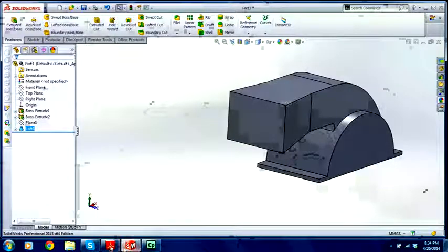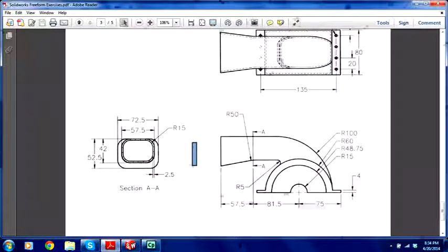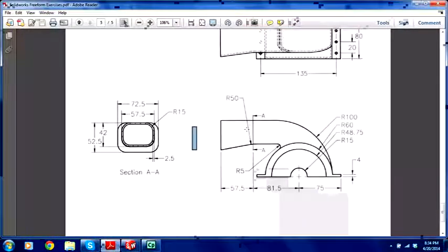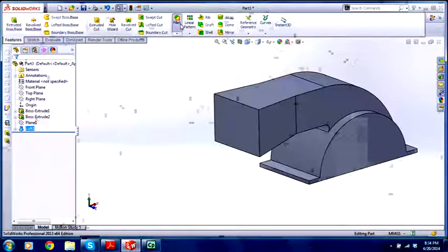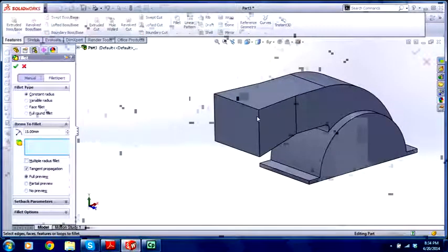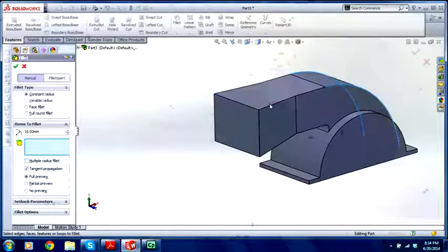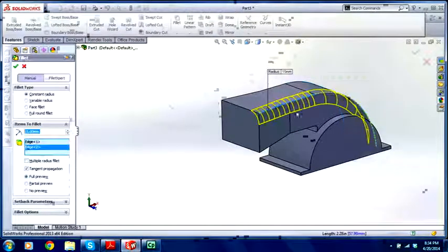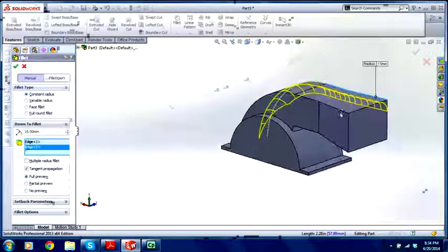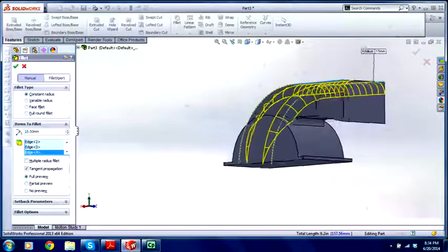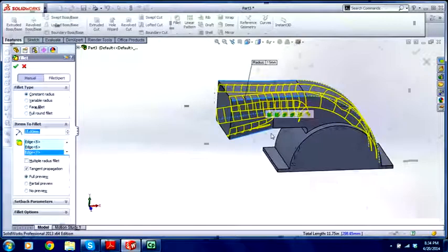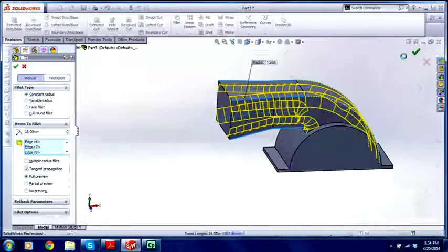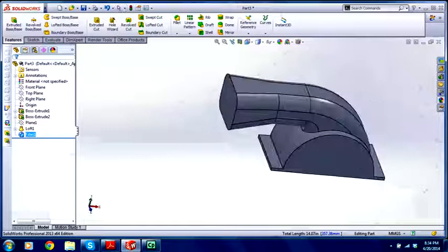You're saying to yourself, well, the front of this is all curved, so we need to add some fillets. So what is the radius? A radius of 15. Okay. Now watch this. I'll get a fillet. I'll make this 15. I'll go 1, not the face, just the line. There's 1, 2, and it'll follow down. And there, and there. Okay? Look at that.